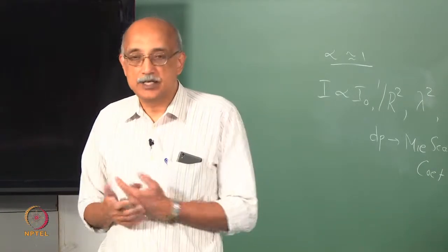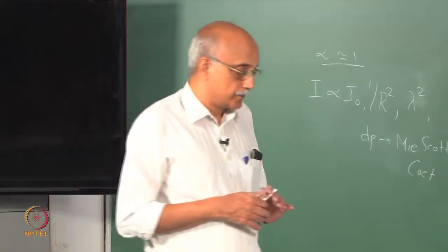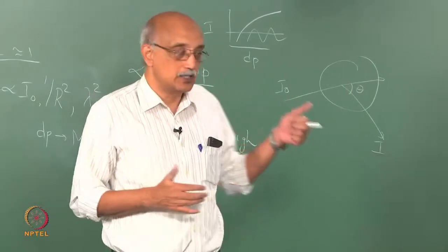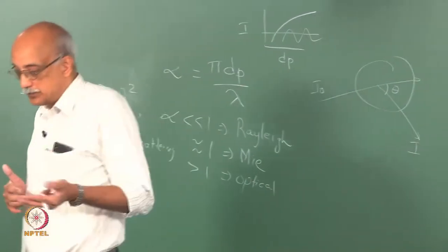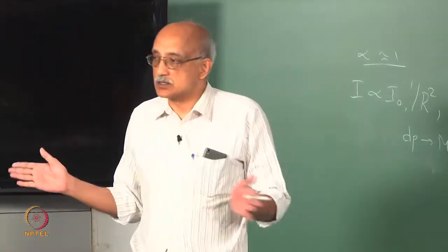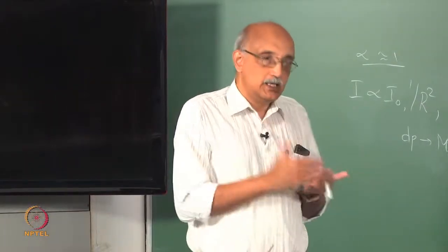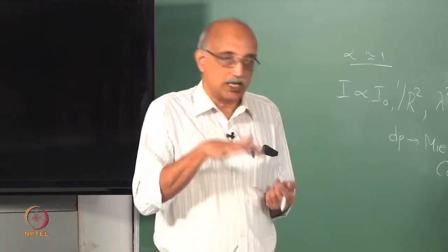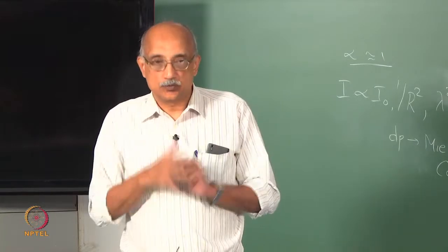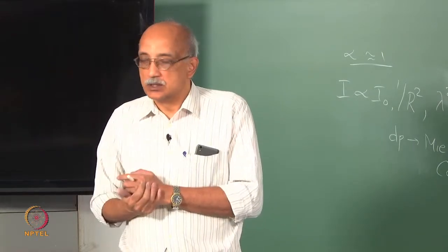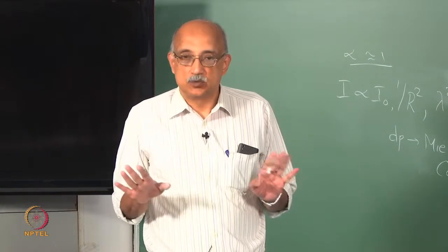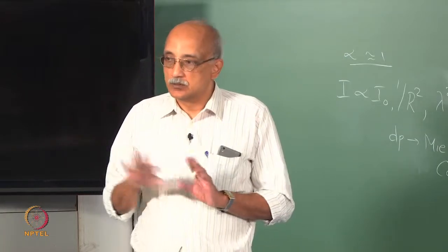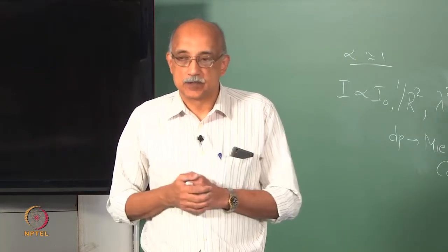L stands for linearity. So let us say that you are measuring these parameters: accuracy, precision, reproducibility, repeatability over a wide range of sizes. How linear are the data? In other words, do you see a significant change in the slope when you go from one size range to another size range? You do not want that typically.